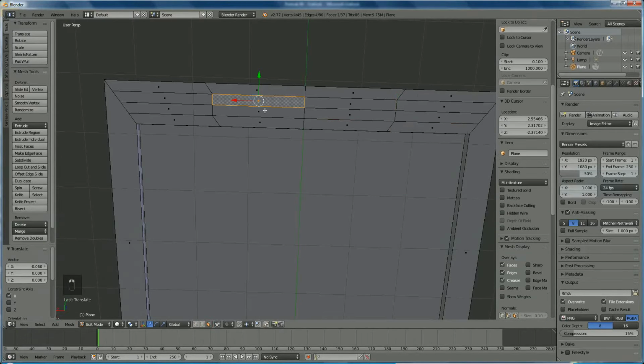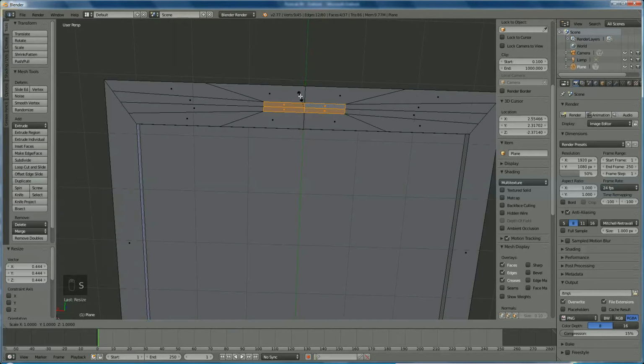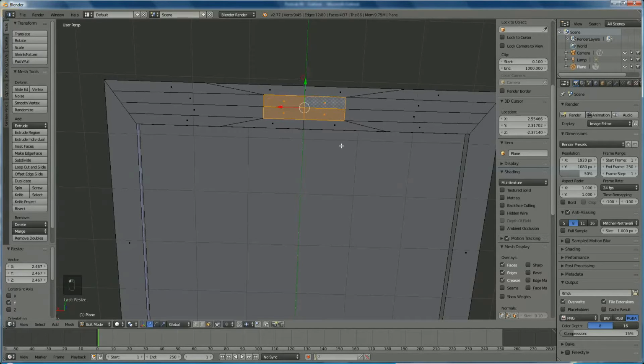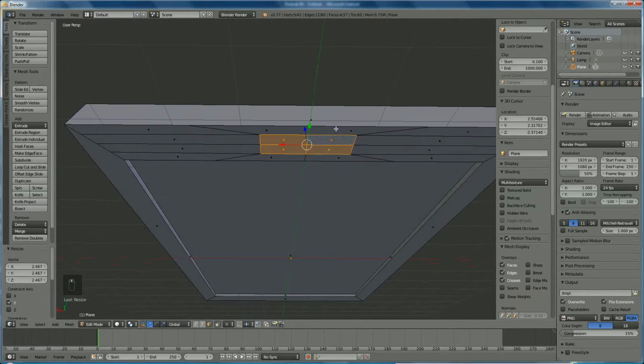Select these 4 faces while holding down the shift button and say shrink. Okay, we're going to extrude them in Y direction, so we press SY. Make them a little larger, like that. Okay, now we're going to enlarge them in Z direction, so we press EZ.